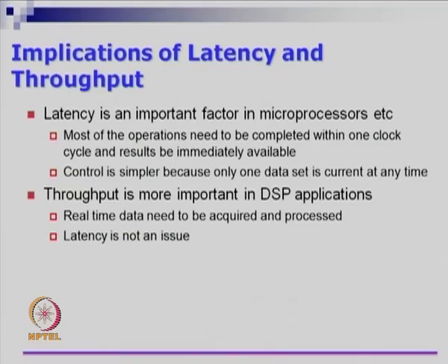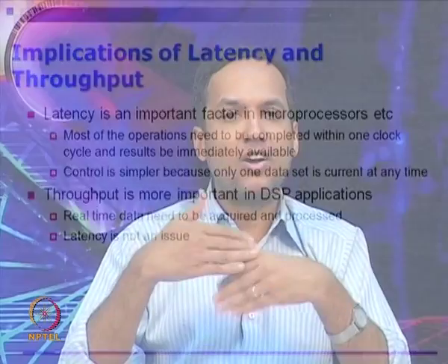So, which means you have to design a circuit that is really fast. Remember, if you are giving only 1 cycle to do addition or multiplication, then we cannot say I will pipeline it and I will get the results after 5 cycles. We need the result in 1 cycle, the whole thing should be combinational and fast enough to accommodate, let us say, 1 nanosecond delay. That is all you can get for a 1 gigahertz clock used for a processor. If you are using a 3 gigahertz or a 4 gigahertz processor, you are looking at either 0.33 nanoseconds or 0.25 nanoseconds to implement the whole adder or multiplier and whatnot.